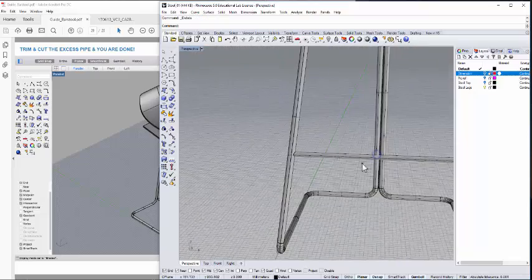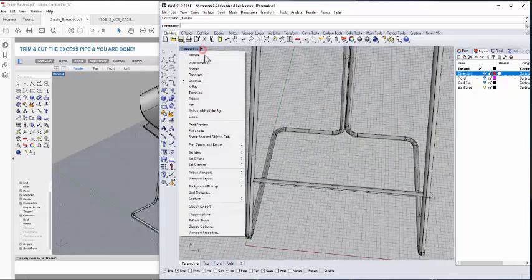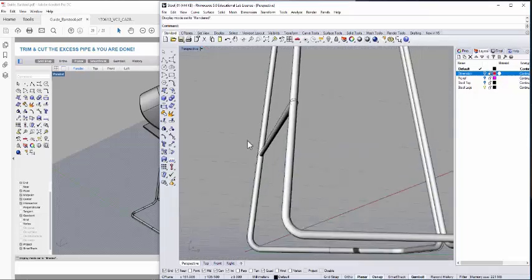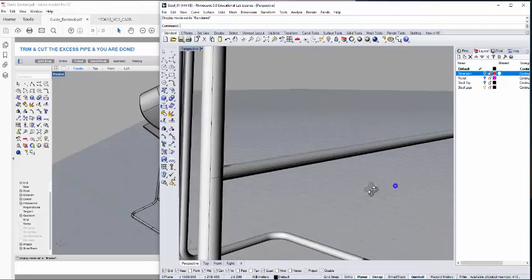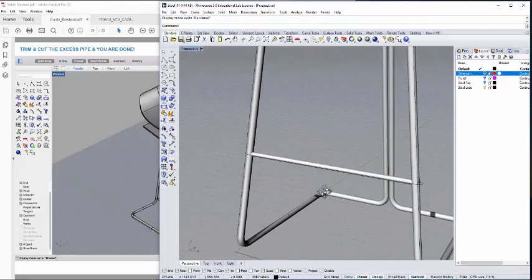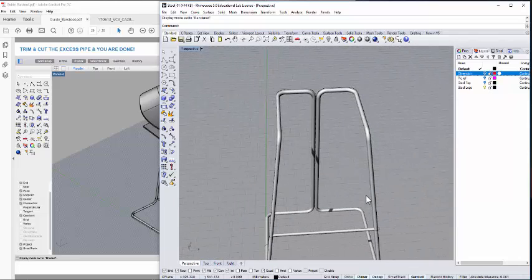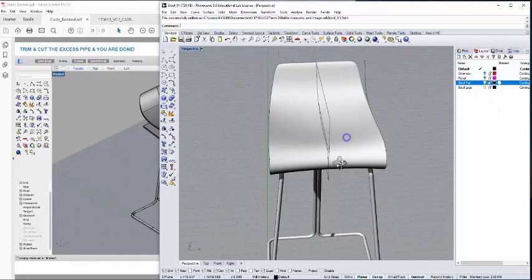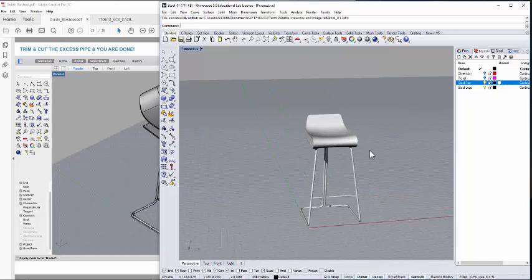So you need to delete to make it much smoother. Let's do a quick render to see. That portion looks quite alright with me. Don't forget to save. Let's show the top. Then let me select all the curves, hide all my curves, do a quick save.